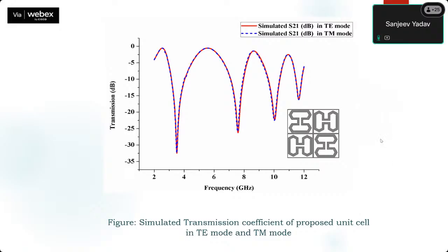In case of absorber for shielding effectiveness calculation, how can we calculate S21? Because generally it is 0. Yes, it is 0 generally, but practically it is not 0, because for S21 in case of absorber we are considering that the copper sheet is on one side, but do you think that all the signals are being stopped? Very few signals are just penetrating it, and they are being reflected or transmitted. The signals are being transmitted. That's the main reason for getting the shielding effectiveness.